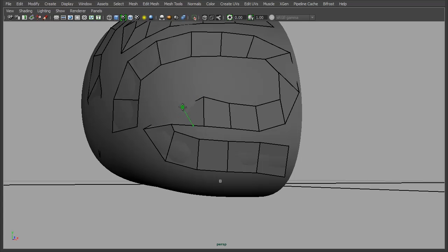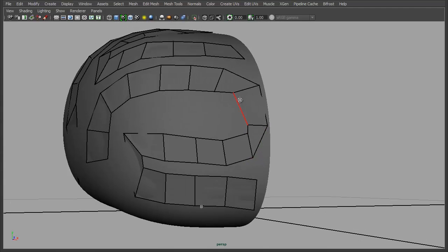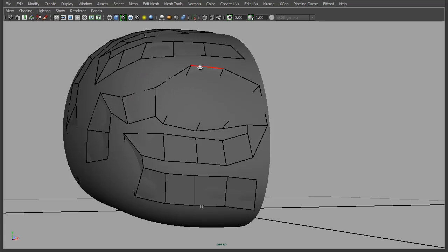In this instance, we can just hold down Control, add in another edge there, like so. Or we could just leave it. If we decide we don't want it, easily just snap it together like so. Move this point down here, this one aligns to here, and so on, and so on. And obviously you could move faces as well, and edges, rather than just vertices.